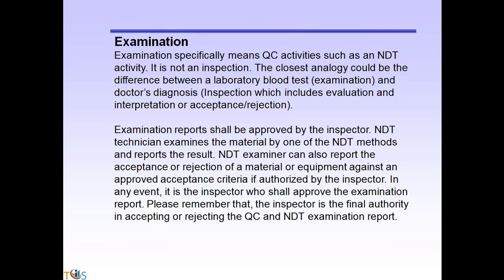Examination. By examination, it means QC activities of a particular entity. It's not an inspection. The closest analogy could be the difference between a laboratory blood test examination and a doctor's diagnosis, which includes evaluation and interpretation or acceptance and rejection. Examination report shall be approved by the inspector.